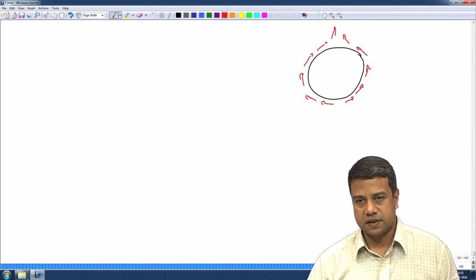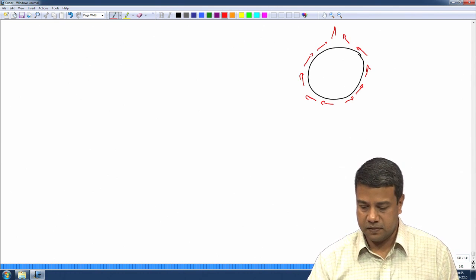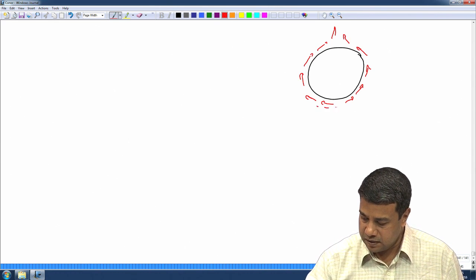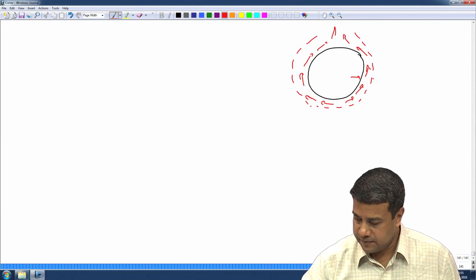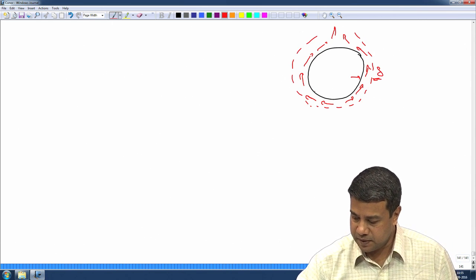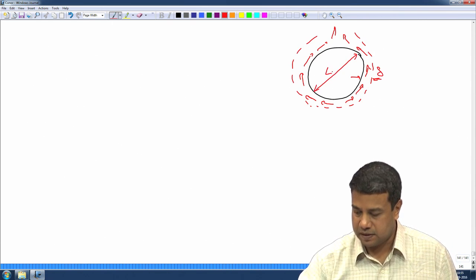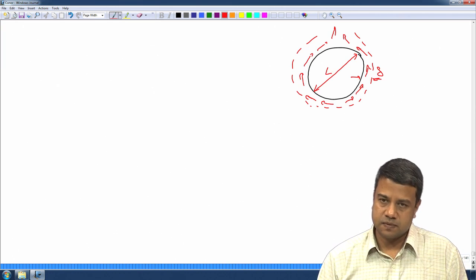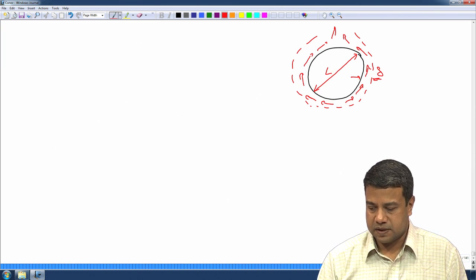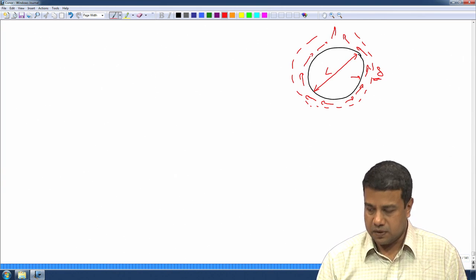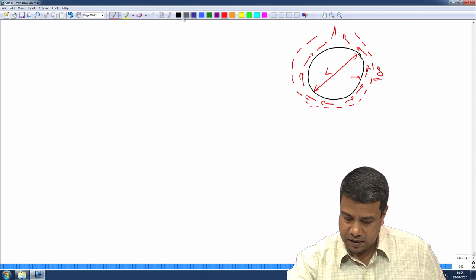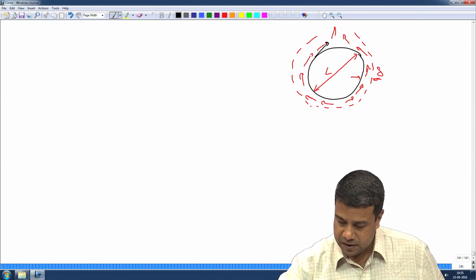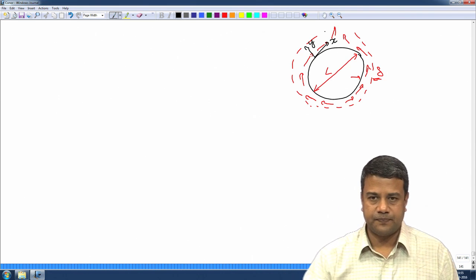However, close to the surface convection and diffusion will become of equal magnitude within a boundary layer of thickness delta, which is small compared to the characteristic dimension L. So, that locally over this distance delta, I can write down a coordinate system in which the streamwise coordinate is x and the cross stream coordinate is y.